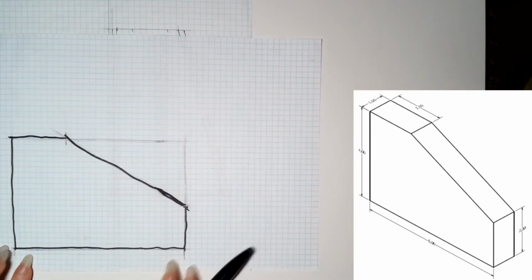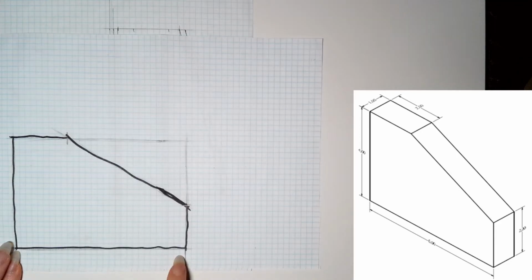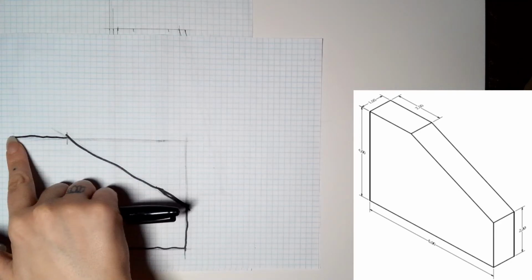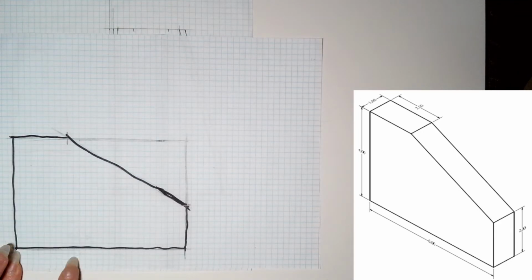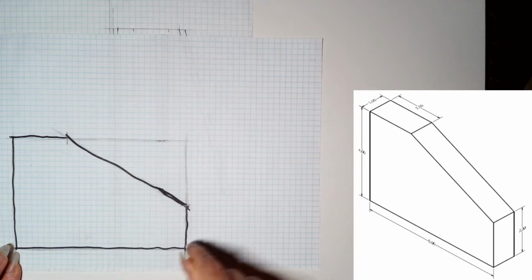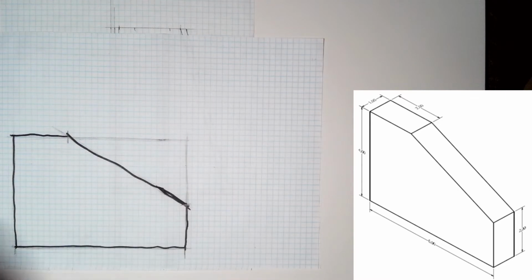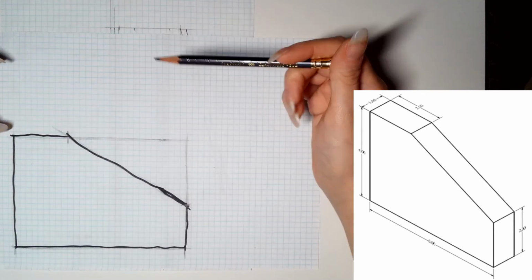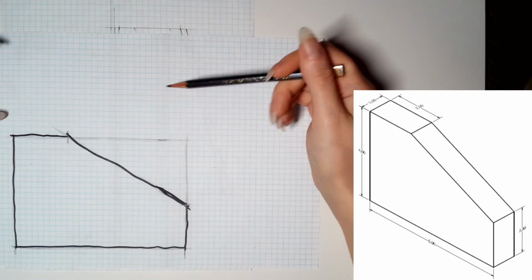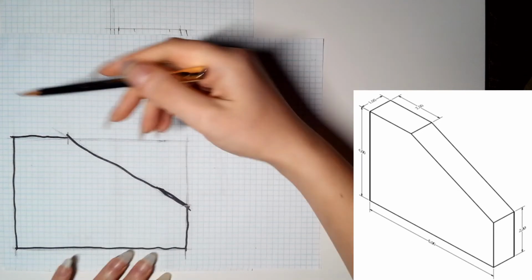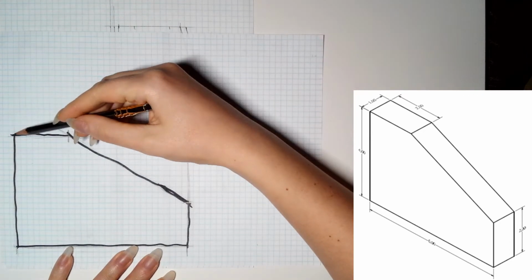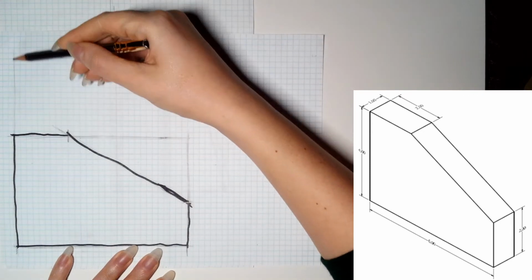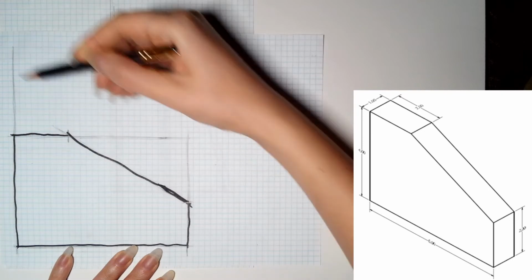So with the front view, I can understand anything related to width and anything related to height, but I can't see anything related to depth. So I don't know how far back any of this object goes. For the top view, I want to make sure that I am aligning it or orienting it right above the front. One way that makes that easier is to project guidelines straight up from here.